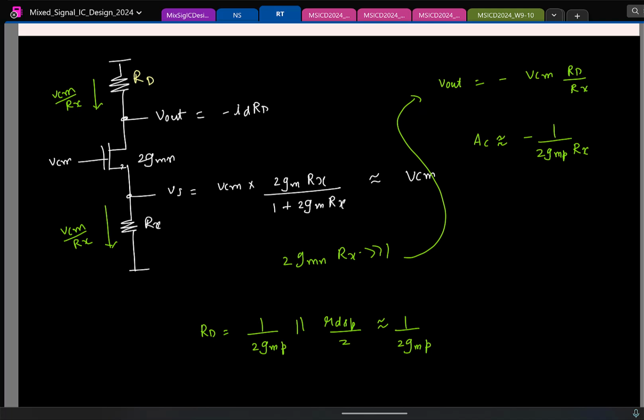No, Vout by VCM, right? It is basically the same change being applied to both of them, correct? Common mode is basically the average of the two. See, it is average, we call it a fancy word and say it's common mode. So if you take the average, it is VCM. So that's about it. I'll end here.